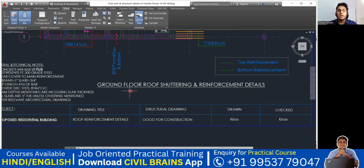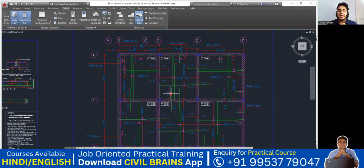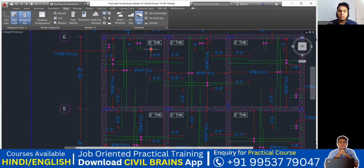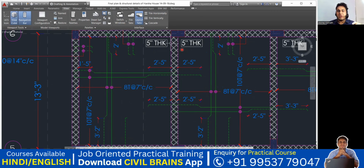Now again, this is my ground floor roof shuttering and reinforcement details. Now, how do you understand the reinforcement? First, this is my entire slab layout. So this is how my slab is going to look. For each slab, they have given the thickness. The thickness of my slab is 5 inch. Like for the beam we have 9 inch by 15 inch, for the slab they give only the thickness, which is again 5 inches here.